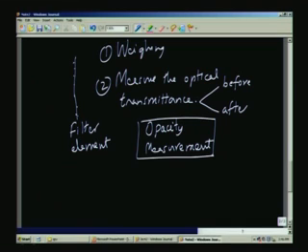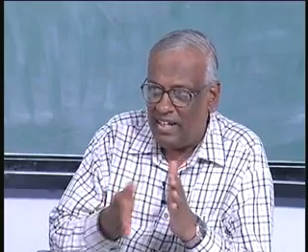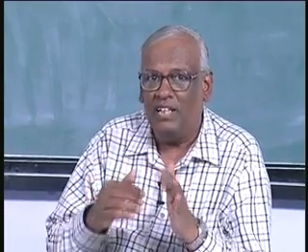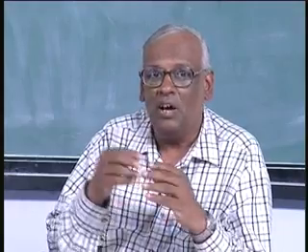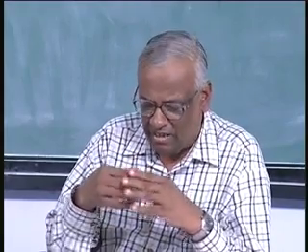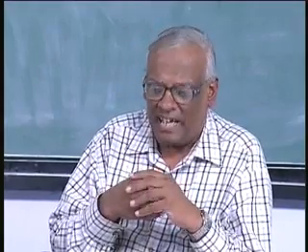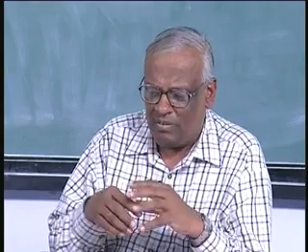Here we have a filter element, and you put the filter element in the path of a light beam, find out what is the transmittance before and after, you get the opacity. But this opacity is now related to the total amount of material which is collected over a given amount of time, and therefore, you have related to the concentration of the dust or the gas particles or the particulates in the original gas sample by using a little bit of algebra.